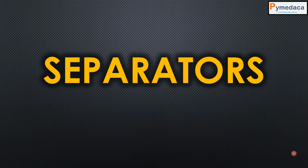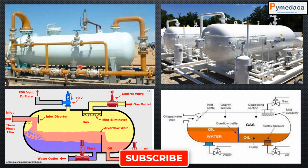Separators are one of the very important pieces of equipment used in oil and gas. Let me tell you the primary function of the separator. The separator separates the water, oil and gases. Basically, when you receive oil into the separator, it gets settled. The water settles because of density, and it will be taken out. The oil moves to the next chamber, from where it is also taken out, and the gas is taken out from the vent, the gas outlet.